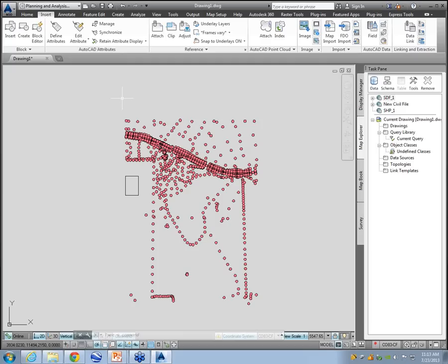And John had a question. Didn't know about the IDX. Oh, the IDX thing? Yeah. I ran into that with a big file. It's not that it'll crash or do anything, for everybody about that IDX file. It's that if you take somebody else's shapefile and you try to read it, and it's got an IDX file, it will take forever to read that file. Delete the IDX file, it'll come up in 2 seconds.